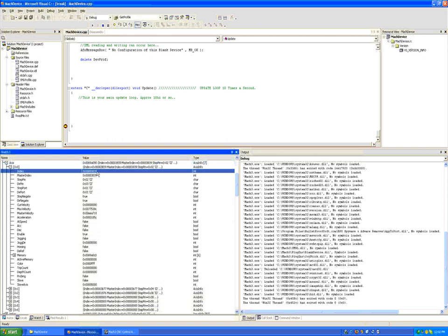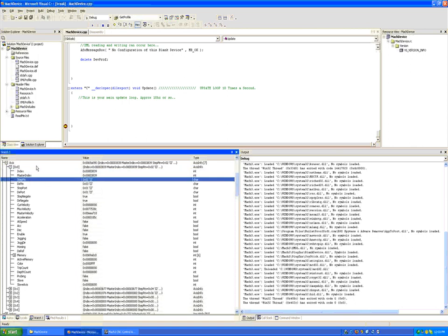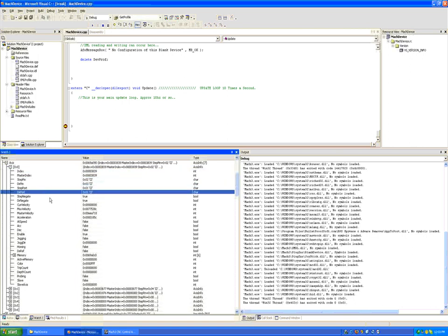We have an index variable. This is the master index of Mach3. This is something that I've said before, I never touch except when you're homing. The index and master index tend to reflect each other, and they only differ in special circumstances that I won't go into unless I have to. We can see where our step pin is for a particular axis, our dir pin, which port our step and dir are on. Are they low active or not?